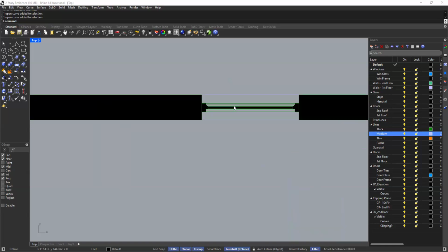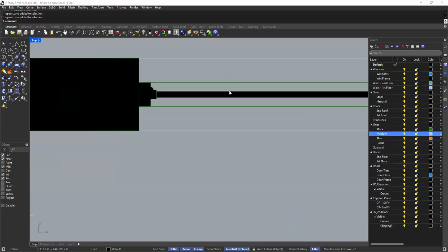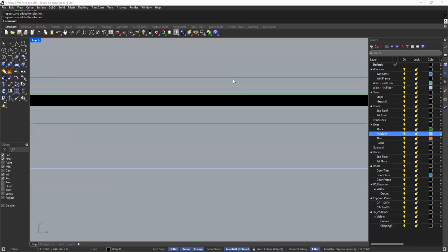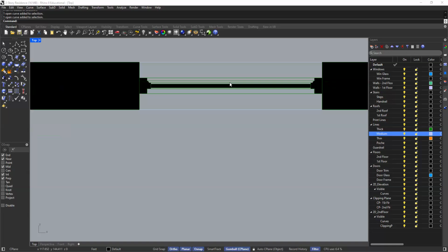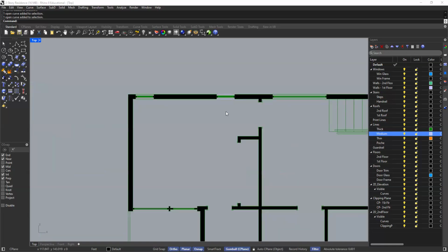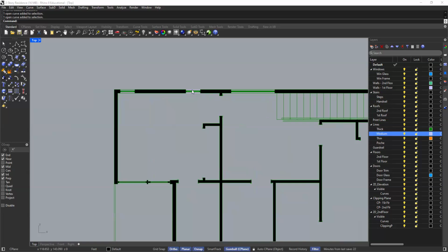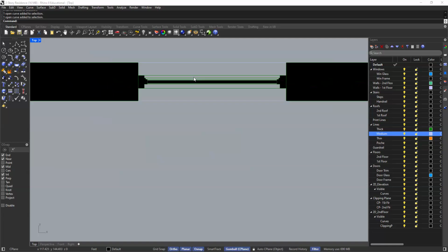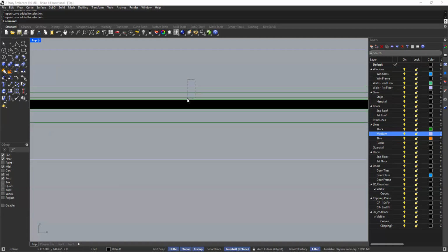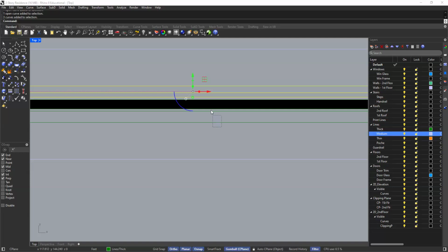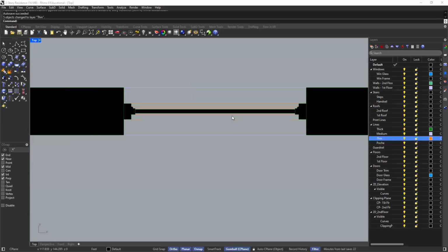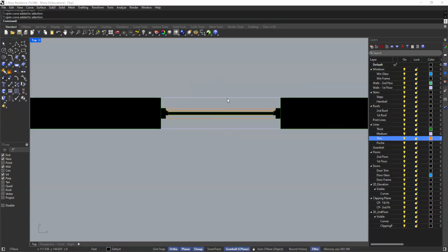However, this is a lot of lines that are close together. So if we place these with a thicker line, then that means that these subsequent lines here are going to be thicker. So they're going to be jumbled up together, right? When a floor plan is taken, this is where we see it. These are going to show up as really thick kind of solid lines because they're so close together. So I'm going to purposely make these lines thinner. Okay, change object layer. They'll be a lot thinner, and then I'll make the sills a bit thicker.